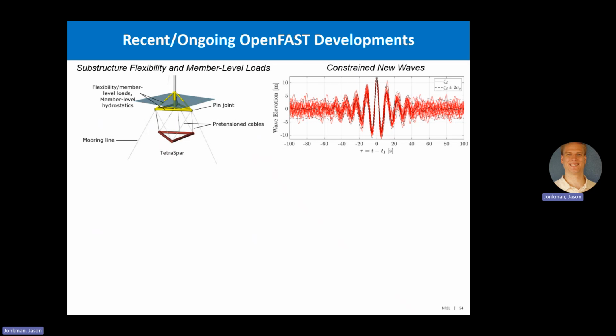You basically have this irregular sea state. And then in that sea state, you can basically say, at this point in time, I want this wave height to hit. Usually it's a factor of 1.86 times Hs or something. But you can define it to be whatever. And this constrained NewWave theory is a cool way of looking at sort of the low probability statistics.